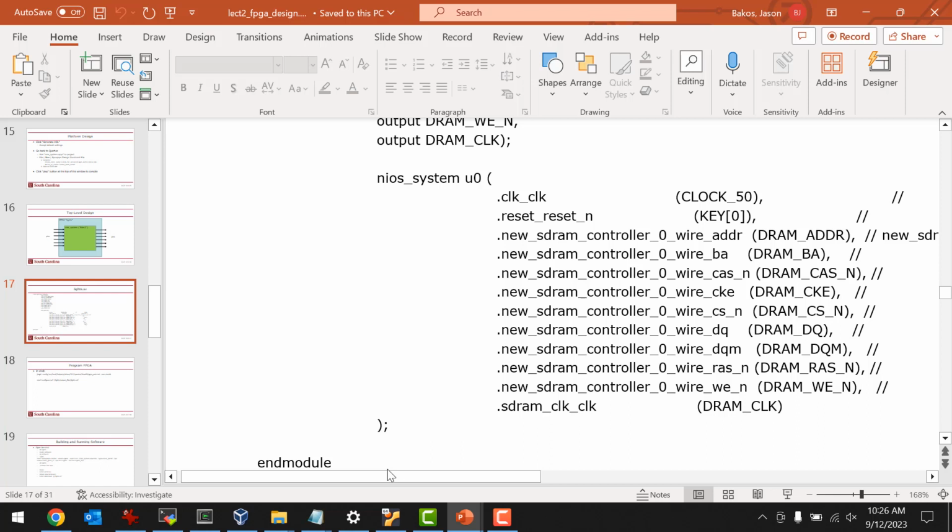And the boundary scan is just there. It's hard logic. It's not soft logic. It's not FPGA. It's not logic you can touch or even see, because it's built into the fabric of the FPGA. There's a JTAG chain that worms its way all throughout the FPGA, and the JTAG UART that you add in the design hooks into that chain. And remember we talked about how JTAG has different instructions, right? So there's different instructions that you can load into the address register in JTAG. That UART carries the UART through that JTAG instruction somehow.